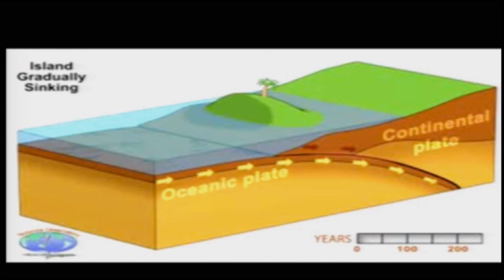So, tsunami waves can also form because of a submarine landslide. If there is any slip, or landslide material is poured down into the ocean along the coastline, then that can also generate tsunamis. But those tsunamis will be local tsunamis and will not have a very wide effect in terms of area. But if the tsunamis are triggered by an earthquake and the displacement between the two plates, then it will have a wider effect, covering or affecting larger areas.